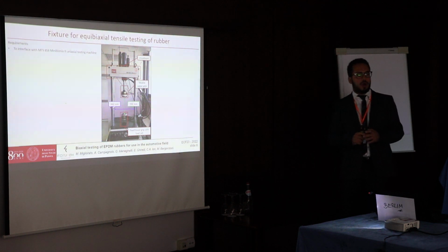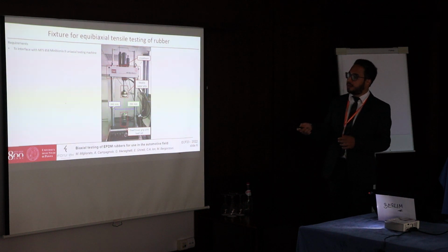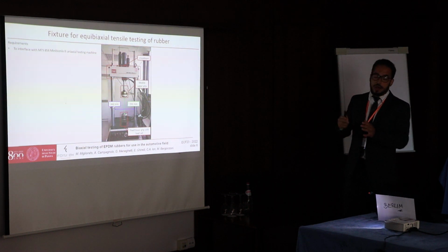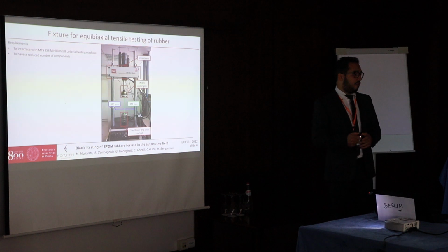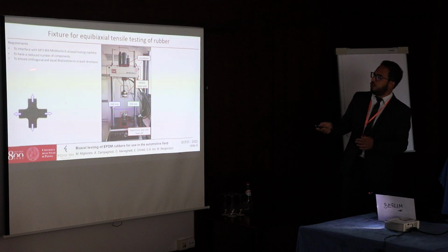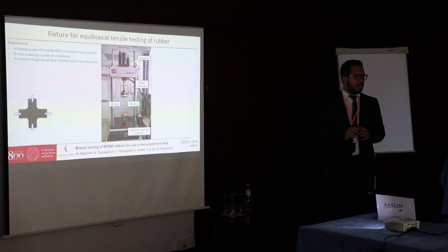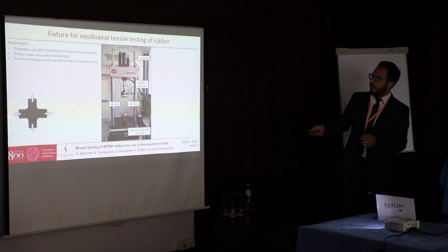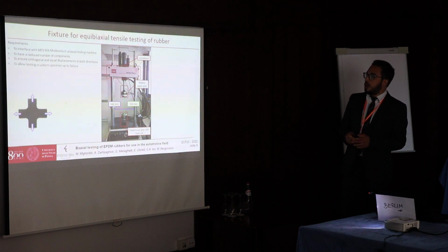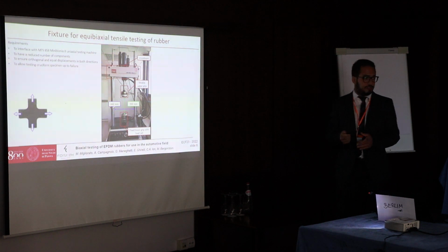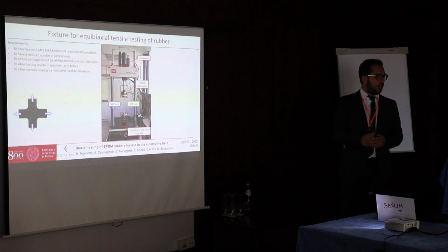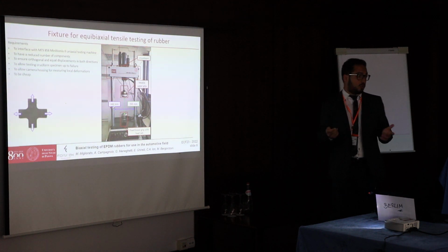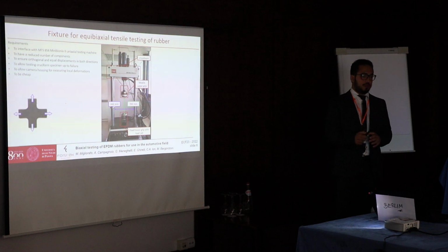The main requirements of this fixture are to have a reduced size to interface with an MTS Minibionix axial testing machine, to have a reduced number of components, to ensure orthogonal and equal displacements along two directions in a cruciform specimen, to allow testing cruciform specimens up to failure, to allow also camera housing for measuring local deformations, and also to have reduced cost.